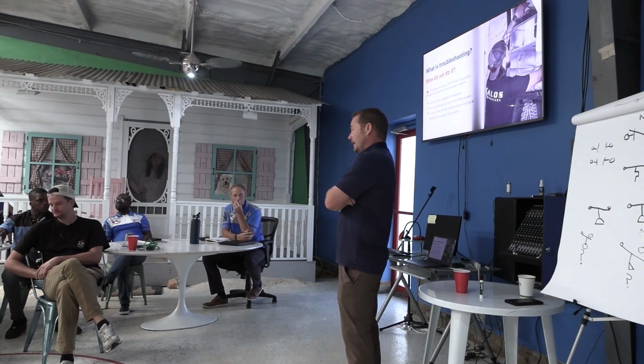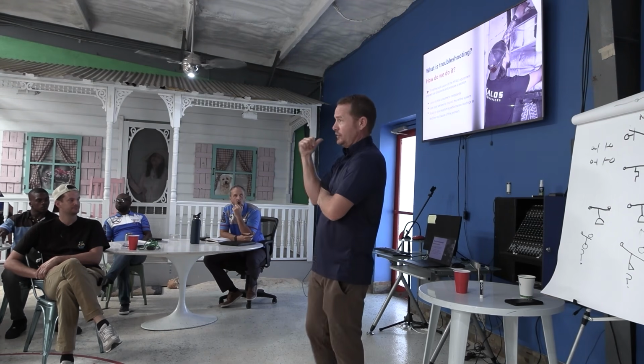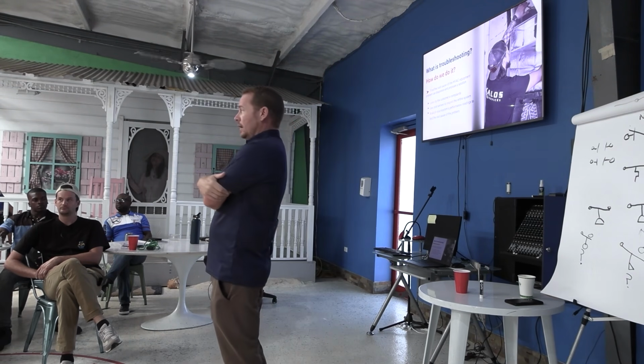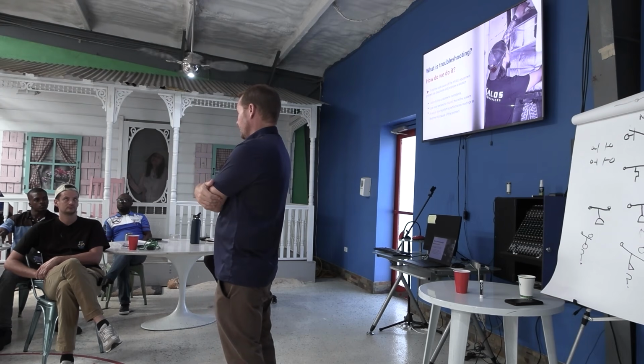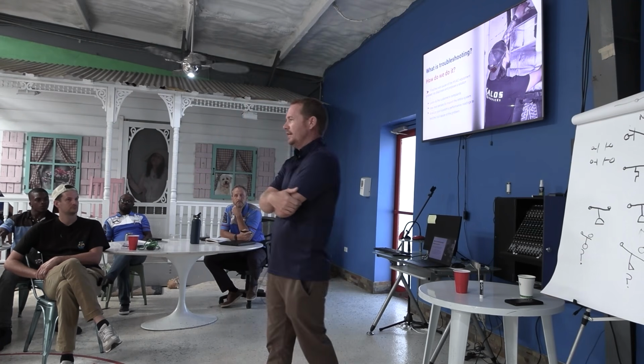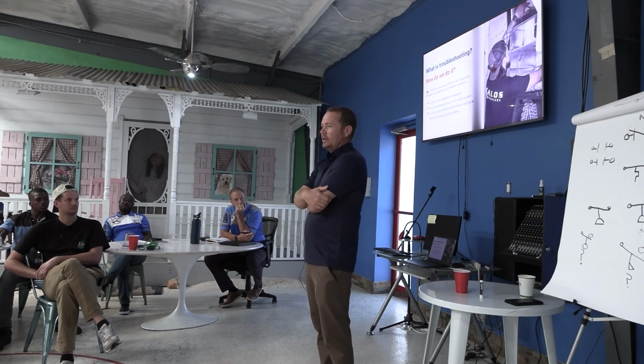Yep, for sure. On the refrigerant diagnostic side, and that's actually what we're going to dive right into now. But to your point, you do need to know what the metering device is nowadays, for sure. And then obviously you go beyond that. Is it a communicating system? Is it an inverter-driven compressor, multi-stage, all that? You've got to eventually know.